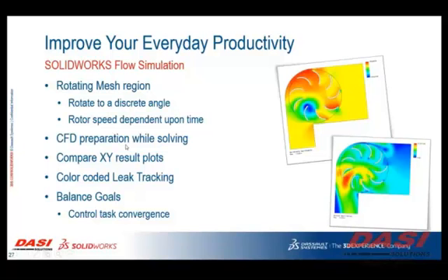We also see the preparation results while we're solving. So much like you saw with the nonlinear that we showed earlier, we're seeing the plots generate as the actual simulation is taking place. Also down here we have color-coded leak tracking, and that's one of those things where gaps that are created in SolidWorks files or any CAD file, frankly, have a threshold of whether they're determined as a gap or whether they're ignored and essentially sealed up or closed during the simulation. Well, the leak tracking allows us to see those legitimate areas and then go ahead and act on those appropriately as well.